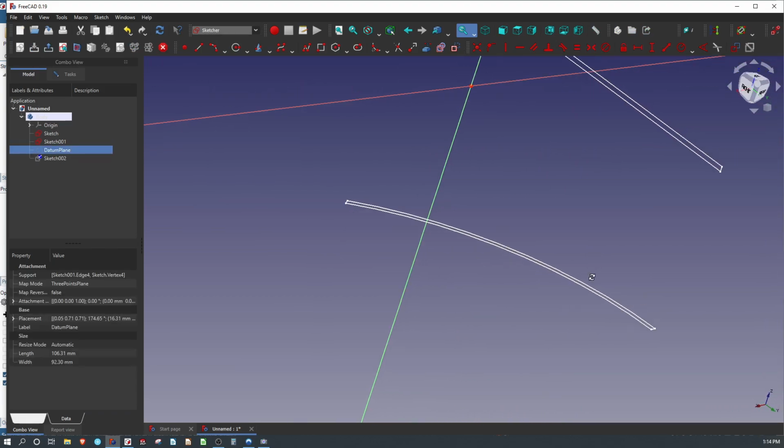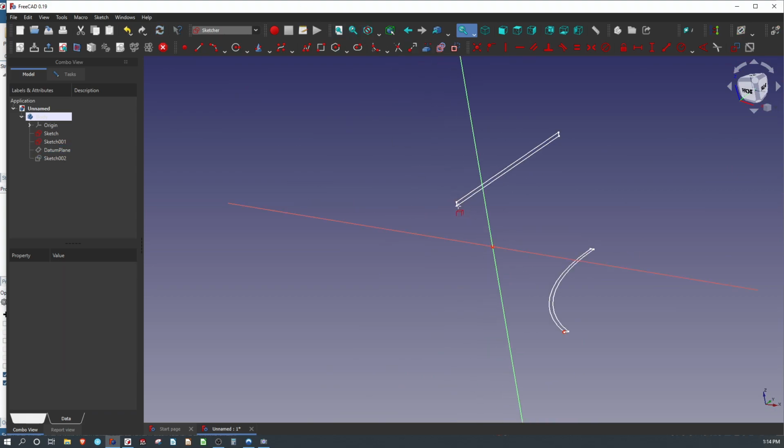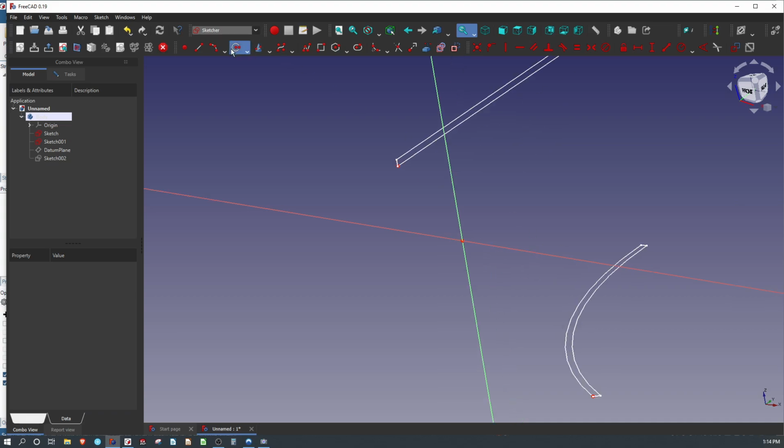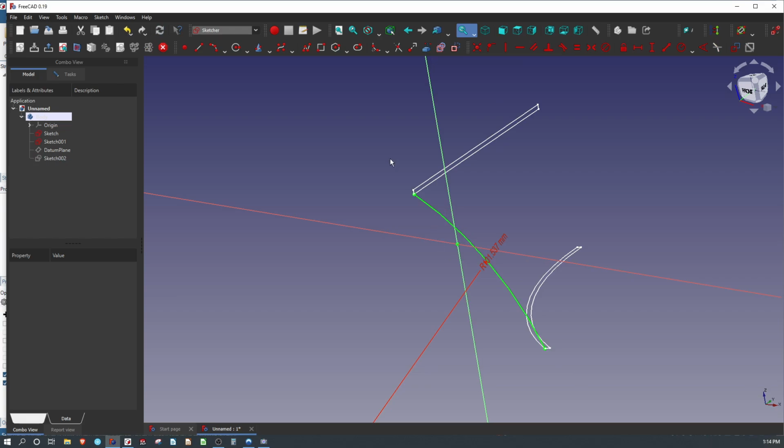So let's do the same thing, but we're going to do it just with these under points. So in theory, right, because there's a 0.0625 difference, we're going to say Shift R 4 times 25.4 minus 0.0625, and that should be theoretically an equivalent radius.